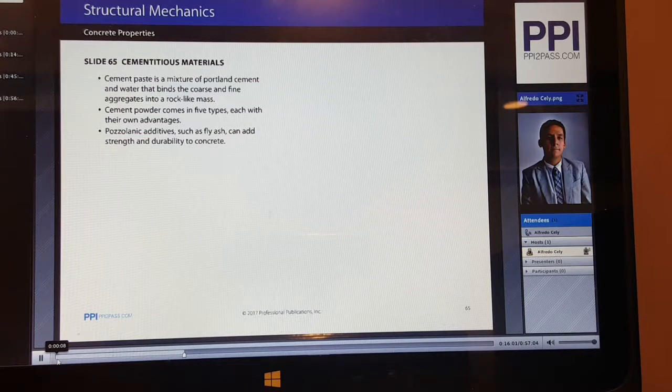Cement paste hardens during the chemical reaction of water and cement, which is known as hydration. During this process, the chemical reaction between the water and cement will release a lot of heat. ASTM C150 details the 5 classifications of Portland cement, and you can also see this in section 48.2 within CERM.